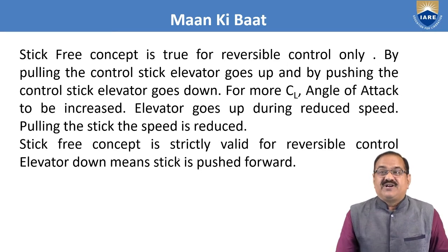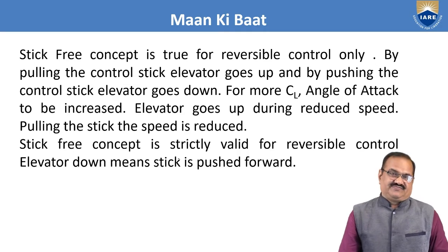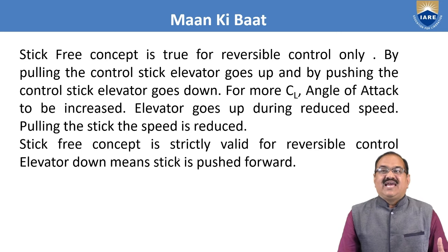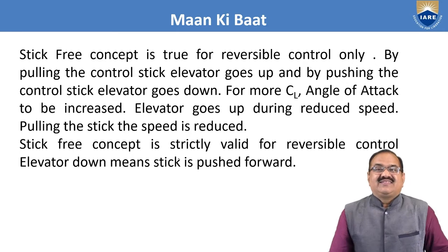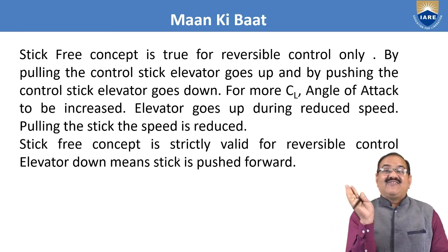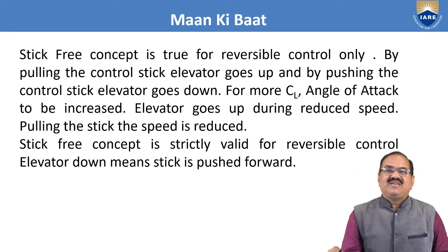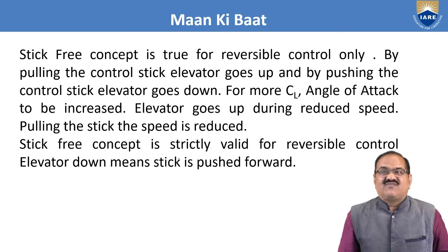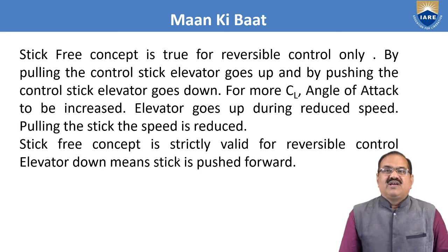If you want more coefficient of lift, then the angle of attack has to be increased. The elevator goes up during reduced speed. So if you want the speed to be reduced, then the elevator has to go upward. If you pull the stick, the elevator goes up and the speed will be reduced. The stick free concept is strictly valid for reversible control.